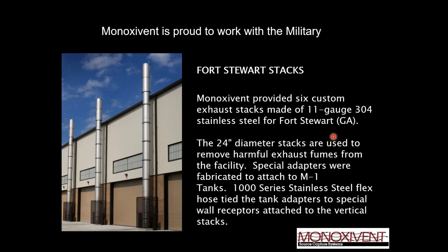In this particular application, there is no blower. What we're doing basically is the velocity of this exhaust at that port is so strong that we're just kind of controlling the air as it comes out through the hose to the duct, to the stack to the outside. So we're able to do this without the use of the fan.